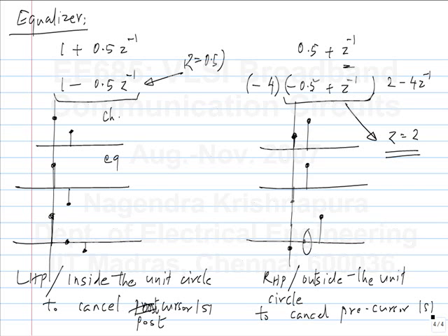Okay. So this is just something to keep in mind, and if you want to cancel both using a linear equalizer, you will need zeros in the left and right half plane. It will give you factors of this type. For instance, in case of the continuous time equalizer, you will have a 0 here and a 0 here.